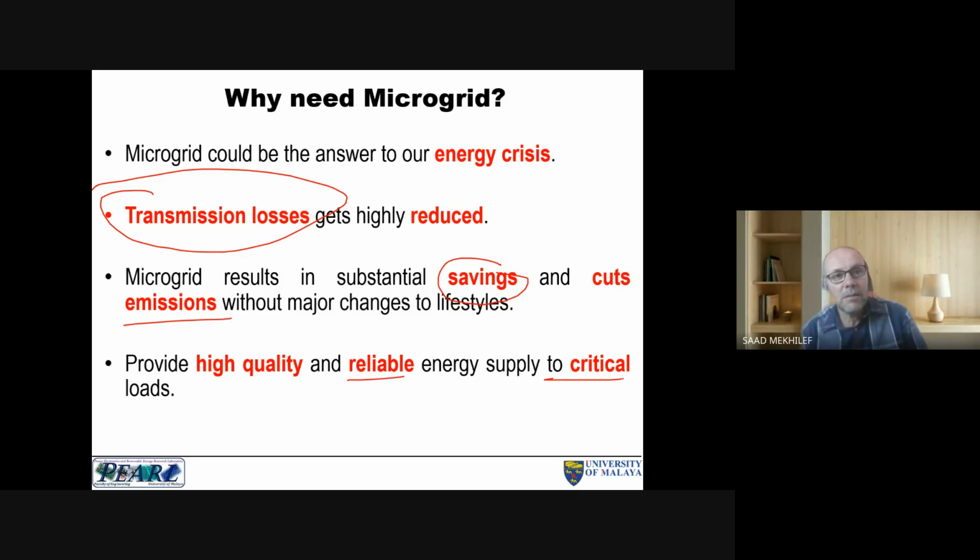Yeah, actually, the combination is meant because batteries and supercapacitors provide a very fast response. Diesel generator will take some time, a few minutes, to turn on. So for the first few minutes, we have the batteries and supercapacitors, much faster. Okay, but supercapacitors have a very low energy density. Okay, they have high power density. Batteries have a high energy density, but low power density.